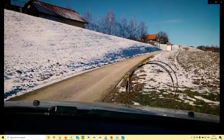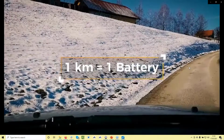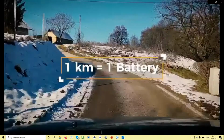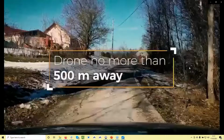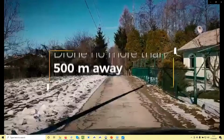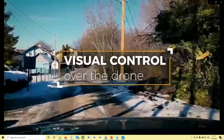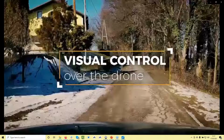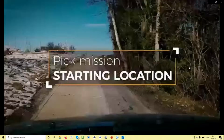When I do road mapping, I usually map 1 kilometer of road with a single battery. I try to start the flight in the middle. This means that the drone is never further than 500 meters from the home point, and I can always have visual control over the drone. And when I do the site inspection, I already try to imagine locations where I could start a mission.